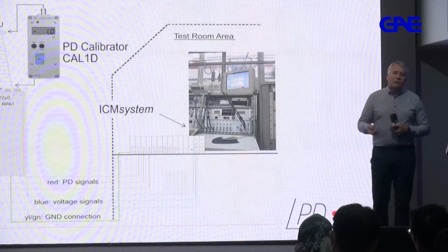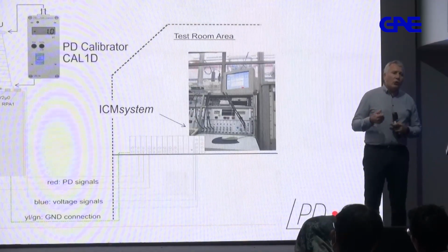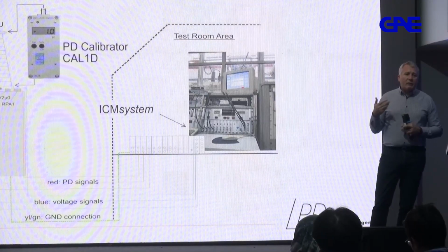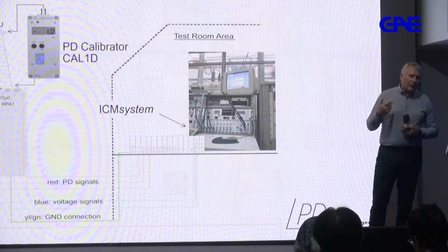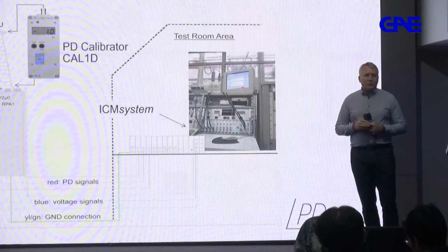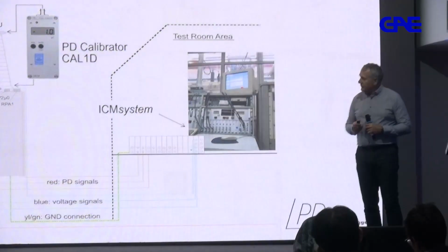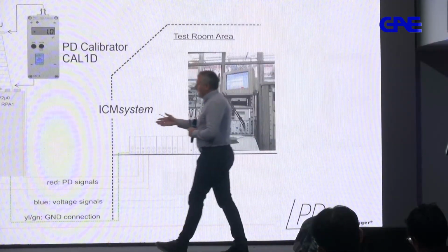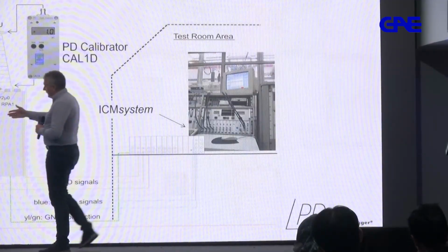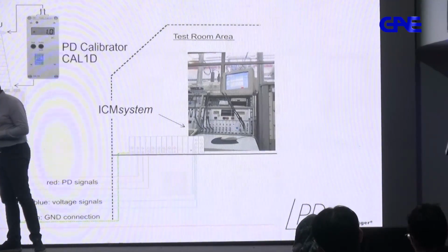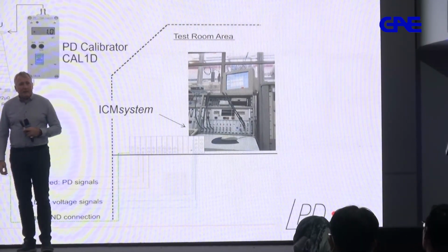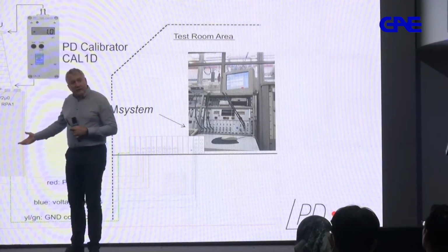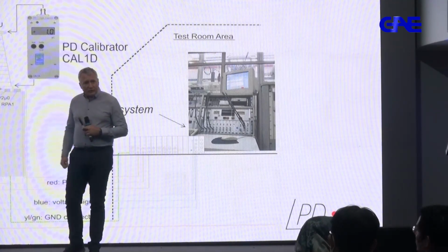So if you are part of a power utility, normally you should always ask for these particular tests, because they are very revealing about the asset that you're about to put in action. So normally here, if you look, you will see the bushing. At the base of a bushing, there is a capacitive coupler that is being used to measure tan delta, but equally it's used for determining partial discharge.